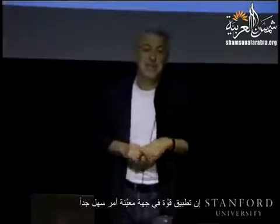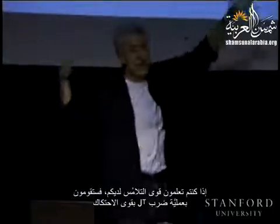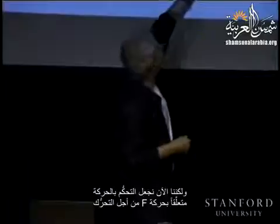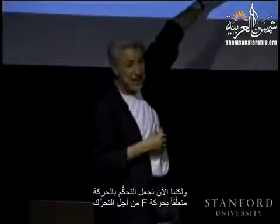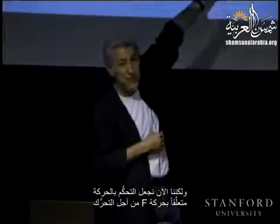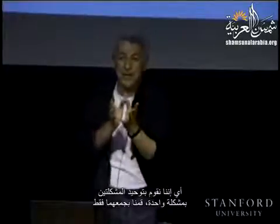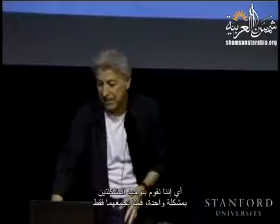To apply a force in some direction, it's very easy. If you know your contact forces, you do J transpose F contact. But now, to move, we are translating the control for motion in terms of F motion. So essentially, we are unifying the two problems. In one problem, you just add them.